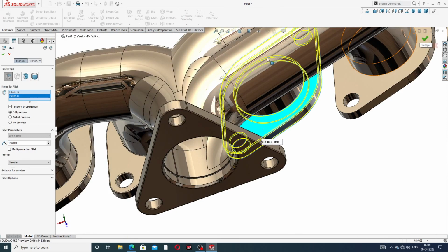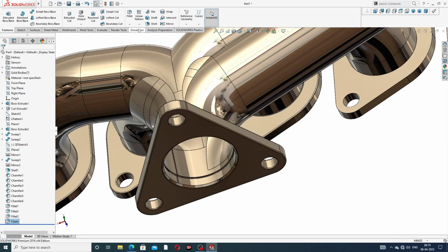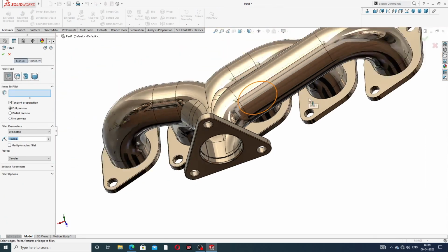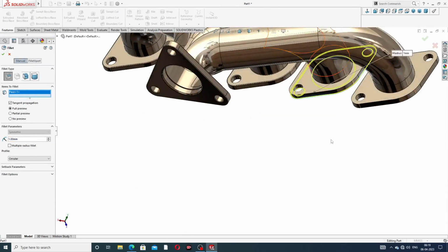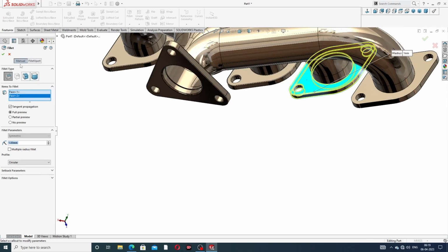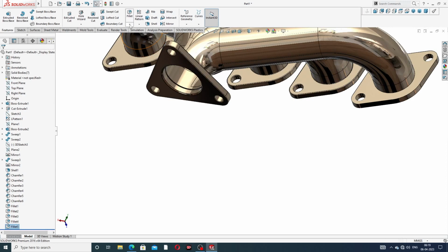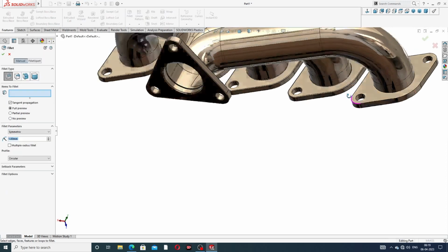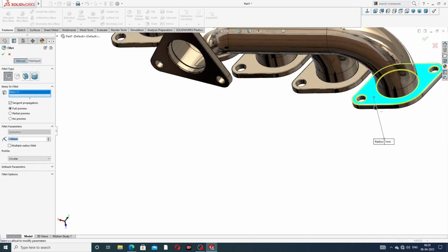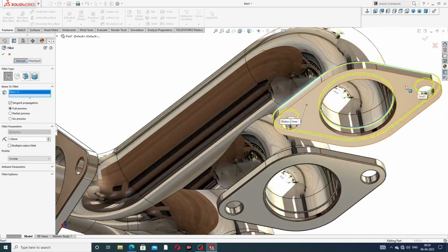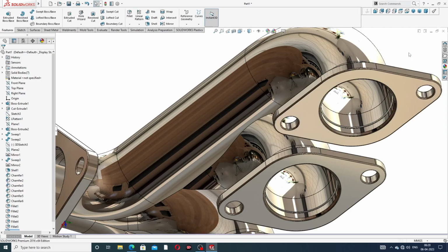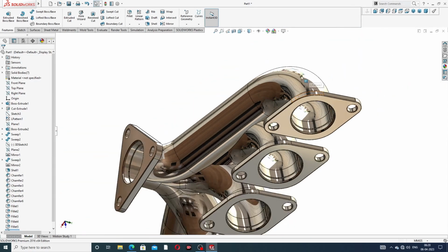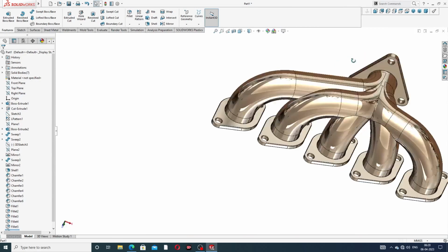Okay, and also use this. Back side and front side, both faces are selected here 1 by 1. And last is a fillet of 1 millimeter, select this face and use the back. Okay, this face, click OK. Okay, all is perfect and correct.